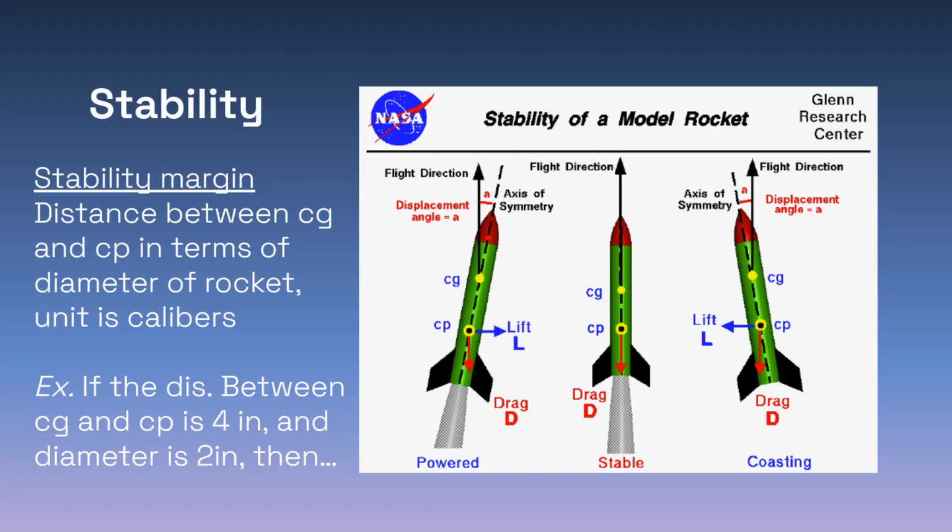Once we get below 2, and especially below 1, you never want to be below 1. If you're in 1.5 territory, in theory, you should be okay. But once you get below 1, your rocket will no longer be counteracting forces such as wind, and instead will be compounding those forces. So instead of readjusting the nose cone to go straight, your nose cone will follow the wind, and therefore it will be blown over, so to speak.